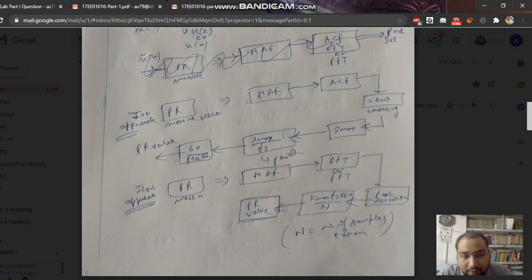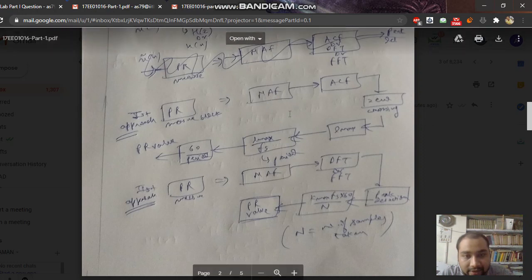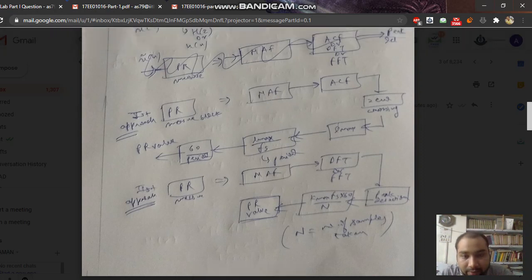As we know, in the autocorrelation function, the distance from the first peak to the second peak will be the time period of the signal, as per the property. So we will use Lmax divided by Fs to get the period, and to convert from seconds to minutes we multiply by 60, so the pulse rate is 60 divided by the pulse period.